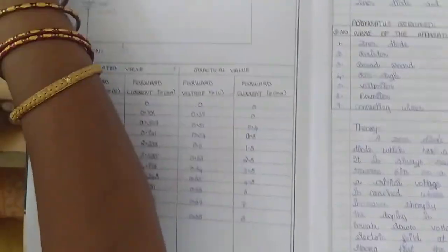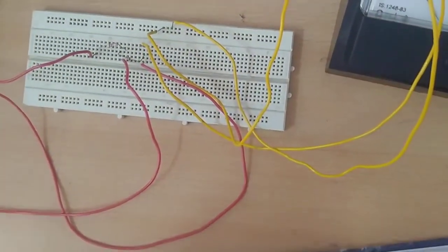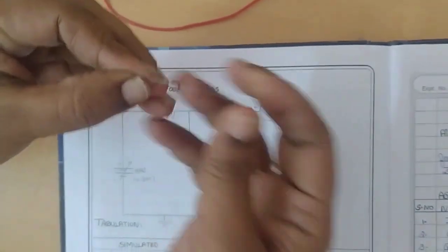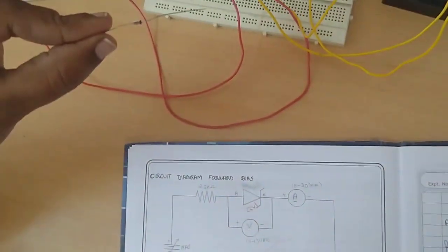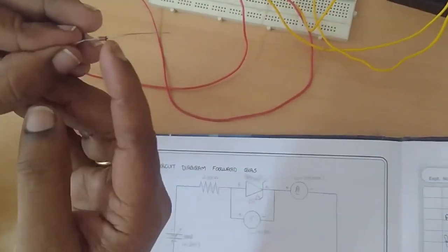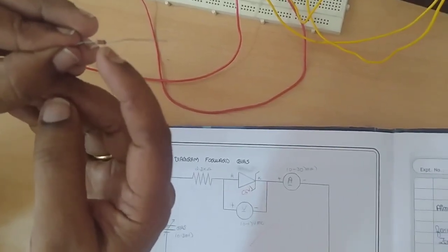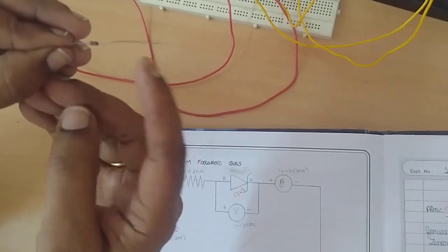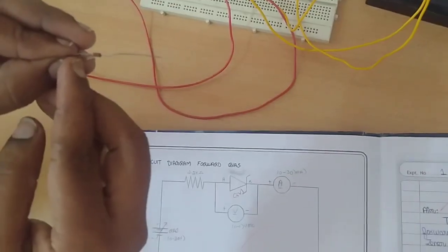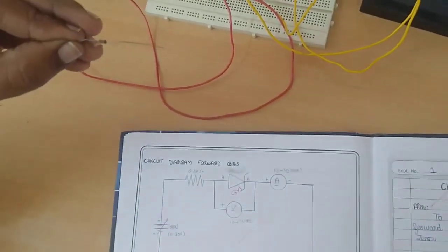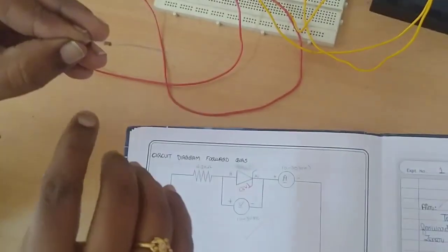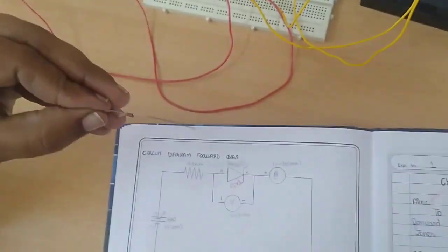And here you can see the practical setup of the experimental setup of Zener diode, and before turning on the circuit you must know the terminals of the Zener diode. So here I am having C5V1 Zener diode, and in this you can see the black coating over this diode. So this terminal indicates the cathode of the diode, and the opposite terminal is called the anode of the diode. So as already I said, the anode is connected to the RPS positive, and the cathode is connected to the RPS negative, which is called forward characteristics.